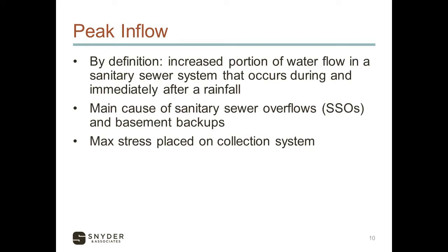Peak inflow is the increased portion of water in a sanitary sewer system that occurs after a rainfall. The graphic that we talked about a few slides ago with the hydrograph, this is really causing the most stress on our system. It's the rapid response that we get from those quick inflow sources. This is really attributed to the main cause of sanitary sewer overflows and basement backups with that excess clear water that's being sent into the system that cannot handle that much water.